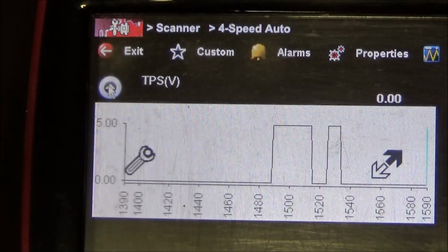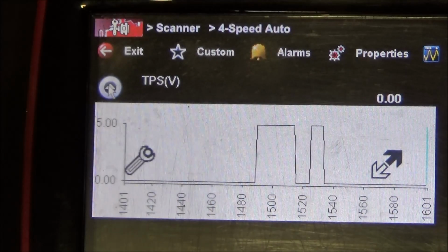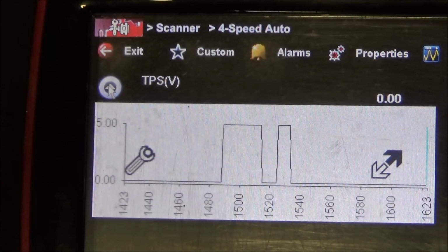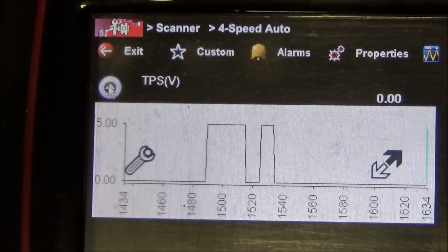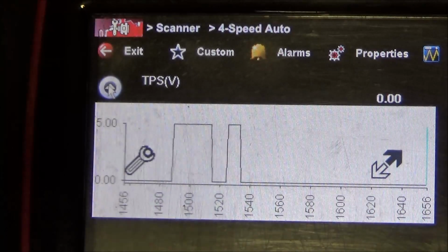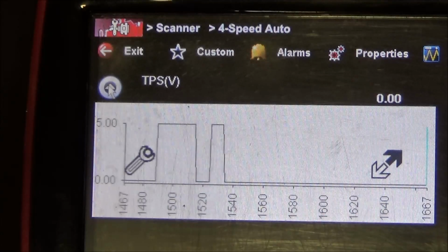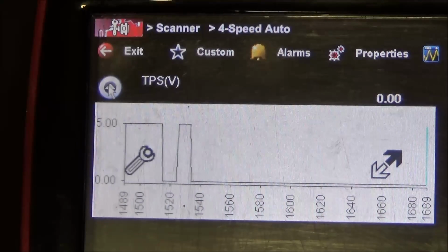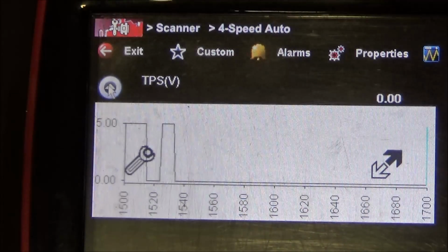You can see that our maximum number we achieved with that is only 5 volts, even though in reality we were really pumping battery voltage in through our test light. That is simply a substituted value by the engine computer, guys. The engine computer is not going to report battery voltage because it does not expect to see battery voltage on the circuit at any time. But that's a very quick, down and dirty test, just to confirm wiring integrity is good on a pull-up circuit design.